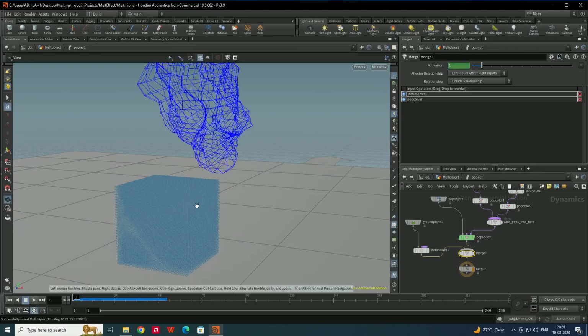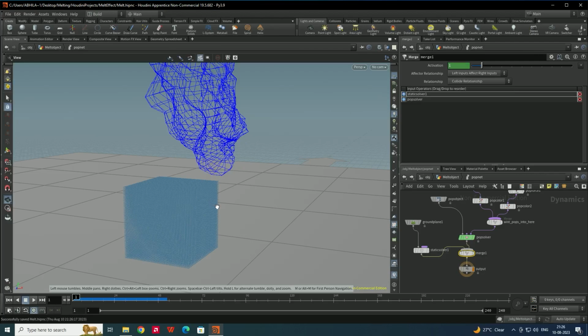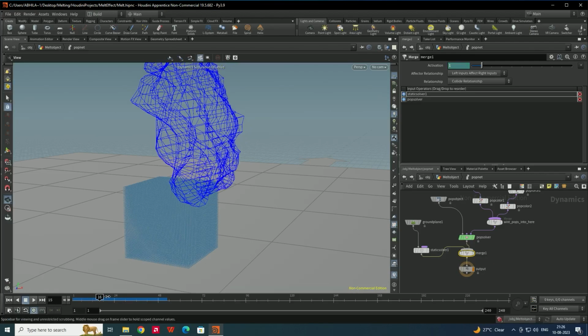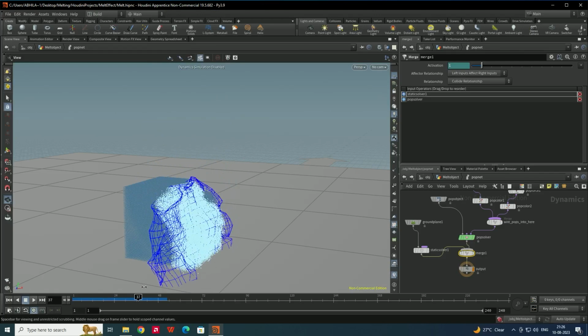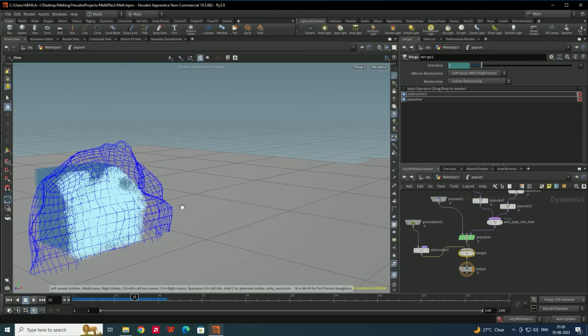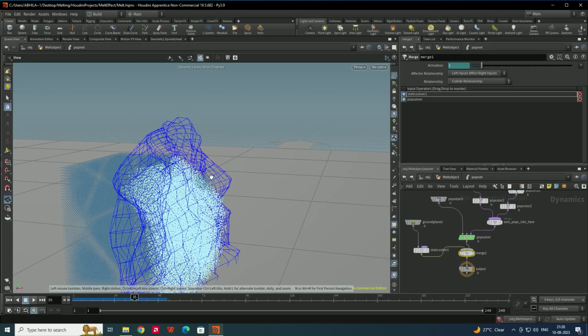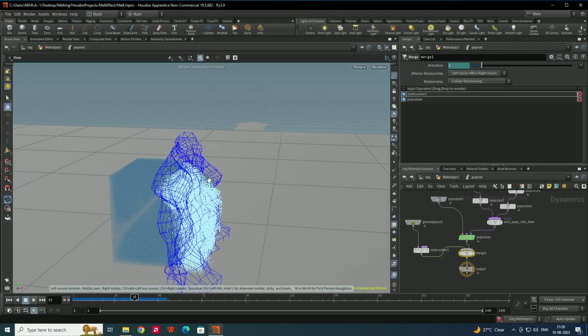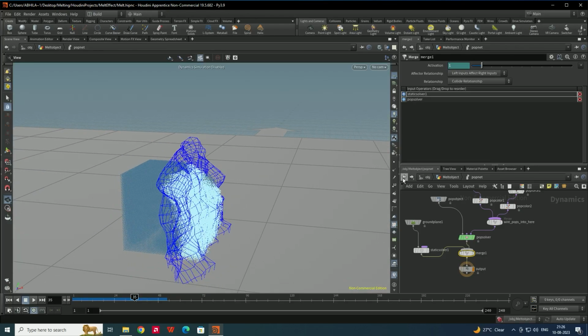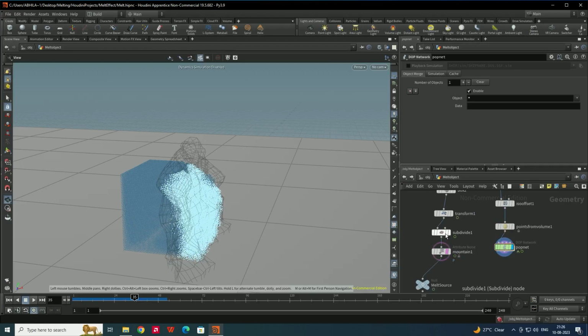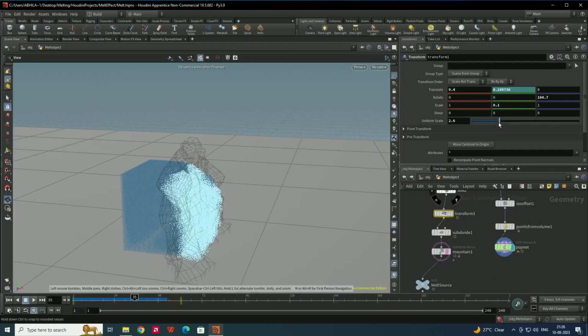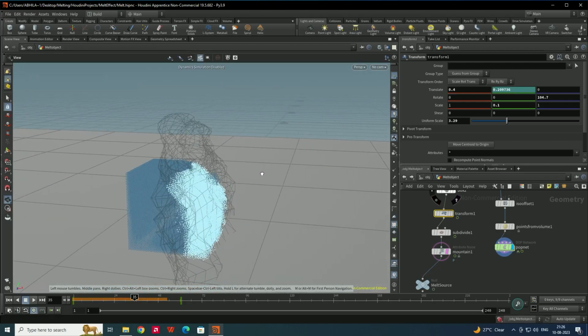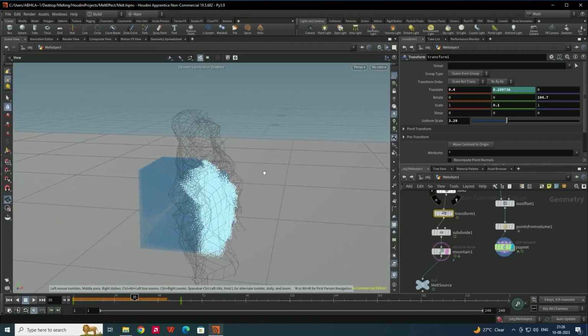So I will go to the first frame and stop the simulation for the time being. So enable this and I will play the animation. Which part is not overlapping? We need to scale this cube over here. So I will scale this thing. So we go back, and in this transform, we can make a uniform scale, so that we'll see whether it is overlapping or not.